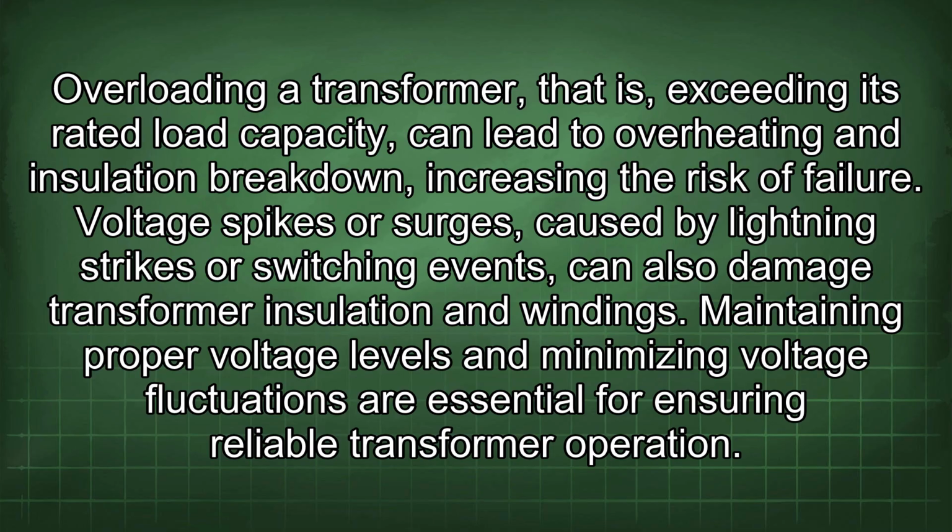Overloading a transformer, that is, exceeding its rated load capacity, can lead to overheating and insulation breakdown, increasing the risk of failure. Voltage spikes or surges caused by lightning strikes or switching events can also damage transformer insulation and windings. Maintaining proper voltage levels and minimizing voltage fluctuations are essential for ensuring reliable transformer operation.